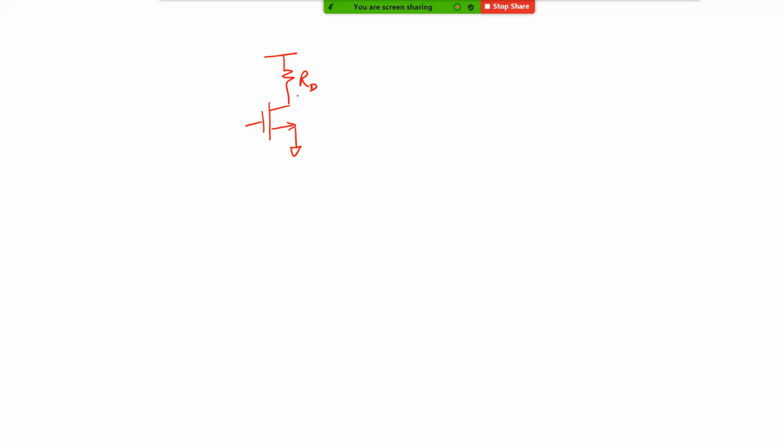Now this LNA is going to get connected to some other circuits. So effectively, as I kept mentioning, you will have a certain load capacitance at the output. The output impedance is RD. Now if you add the CL, what happens to your small signal equivalent circuit? Let me just quickly draw. You have RD and you have a CL.